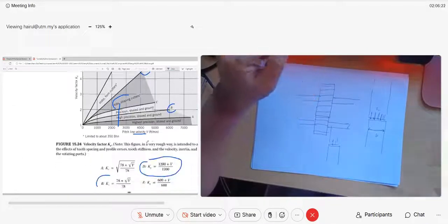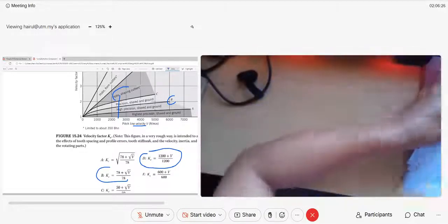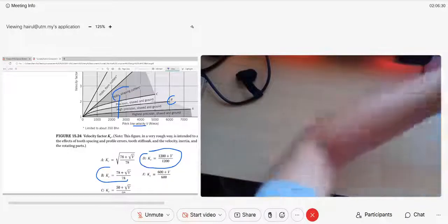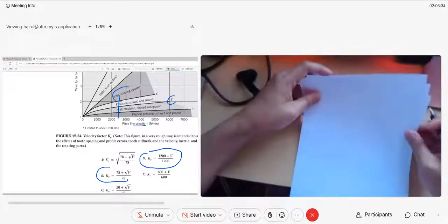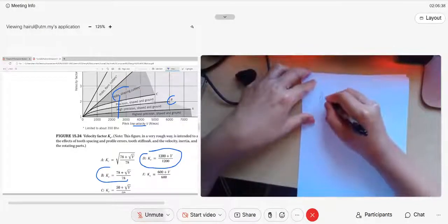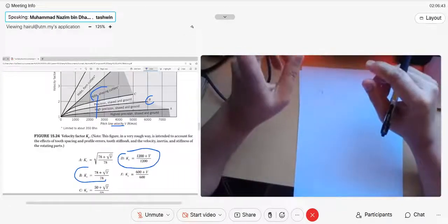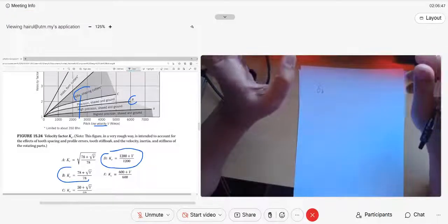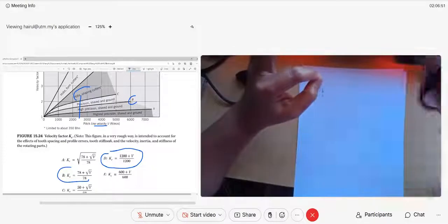So that will be your equation for your bending stress. Remember, class? Your sigma bending, we only calculate sigma bending. We have not gone for SN yet. SN, remember, with CL, CG, CS for your shaft, right? But gear is a little bit different. At the end we need the safety factor, which is your SN over your sigma bending.